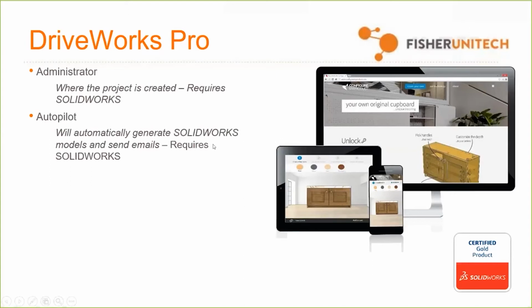Also, you got to make sure you have a seat of SOLIDWORKS that sits with it. And I don't recommend having a network seat unless you want to fool around with the options file and basically say it always gets this license. Other than that, what I would recommend is getting a nice seat of most likely standard, SOLIDWORKS standard, that can just sit right along with DriveWorks Autopilot. And it'll open up standard, generate what it needs to generate, and shut it down. It's kind of like a virtual employee.